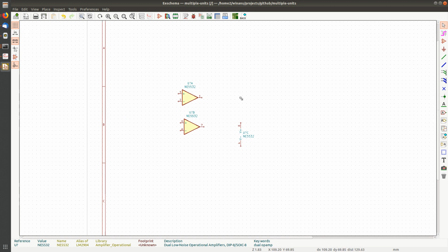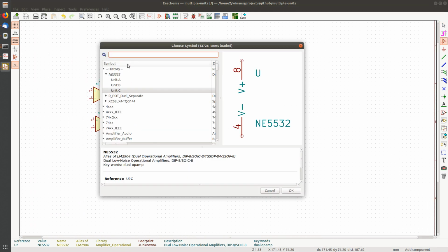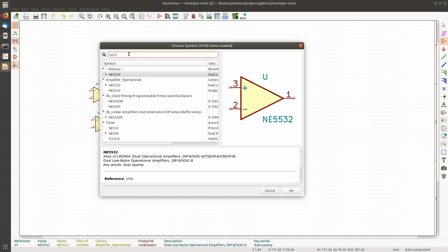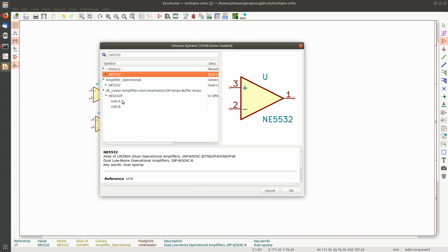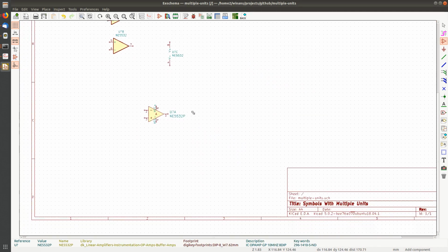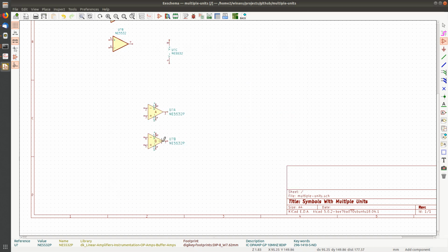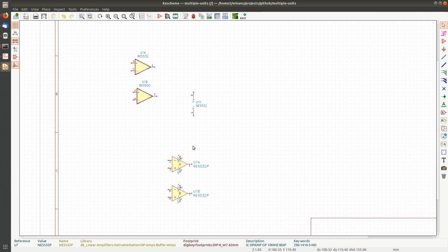All right, now when we were playing with this, you'll also notice there's a variation in the DigiKey library, which is a similar multi-unit part, but this one only has 2 units. So let's look at that one. That's what we've got here. So this, as you can see, is a mixture of this previous one that's in the KiCad library.